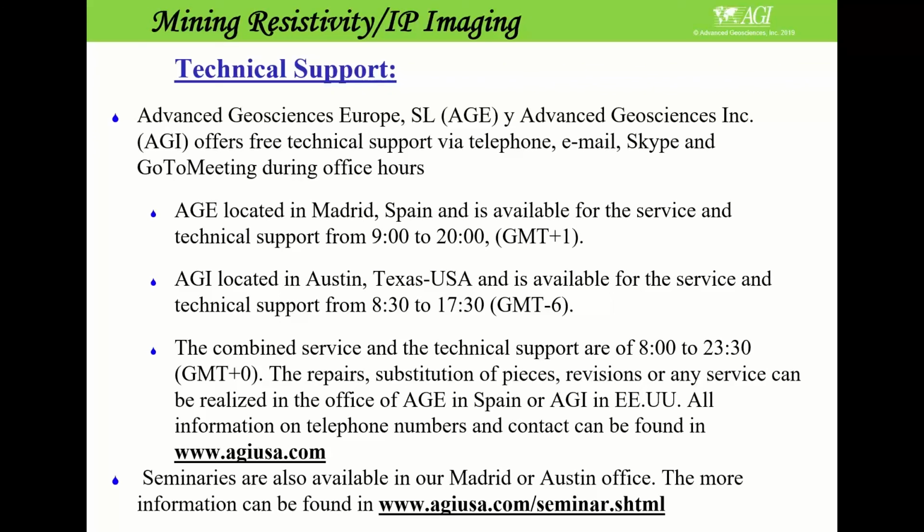But in most cases, if you do resistivity IP, you get the chargeabilities from the surroundings. Typically there are always clay and silt in the area. That clay will give you the chargeabilities, not the coal material.